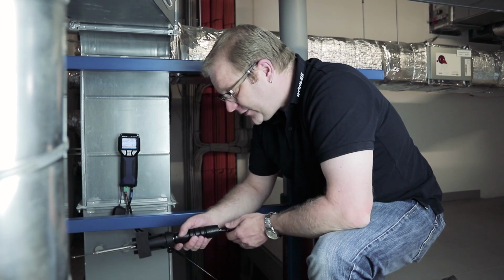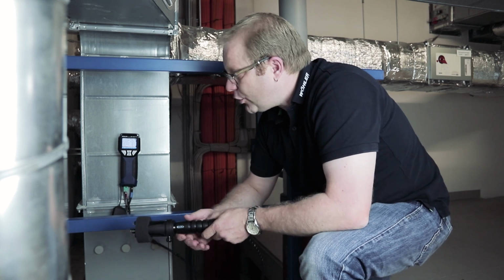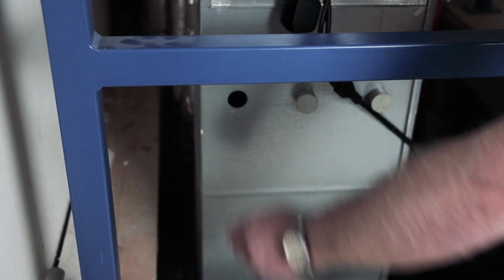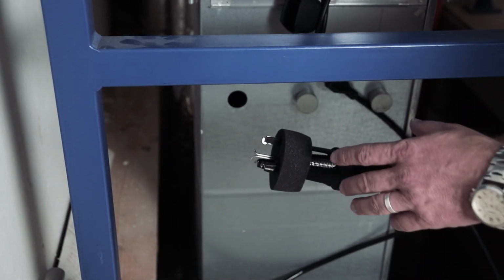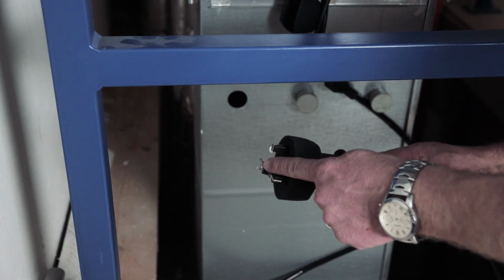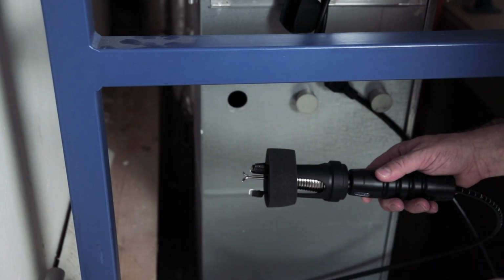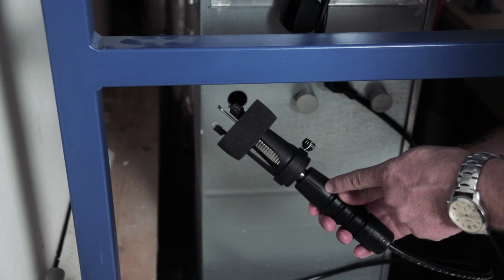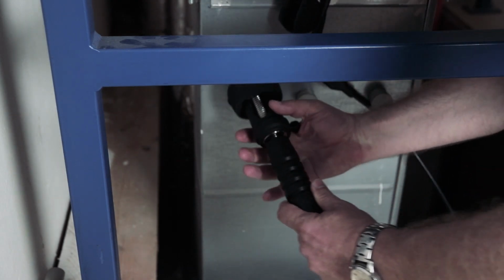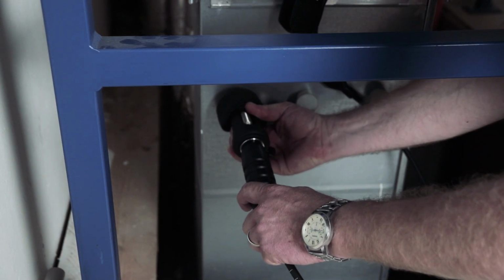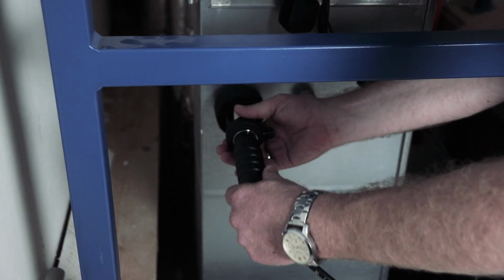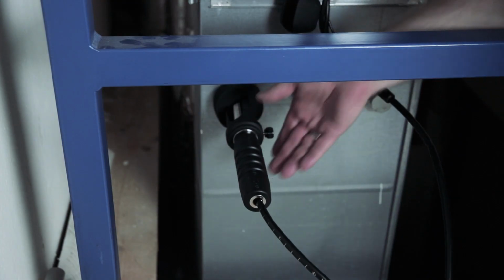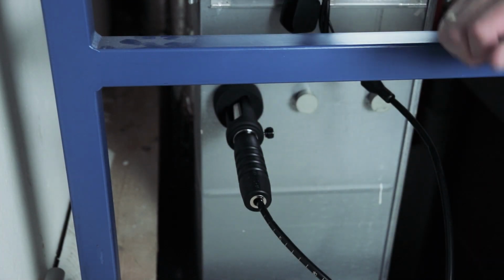So the device is ready. I have already zeroed the pressure and can now turn my attention to the first measuring point. The position of the probe tip in the airflow is of course important when positioning the probe. This is of course logical. The position of this probe tip can also be clearly seen here on the probe handle. This means that I can now go here, insert the probe, and then seal my measurement opening here with the foam. And now I can start the measurement straight away.